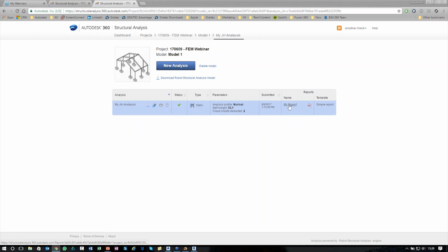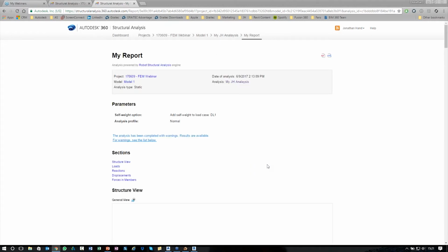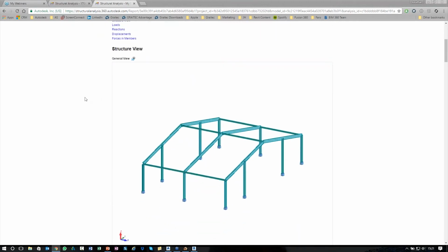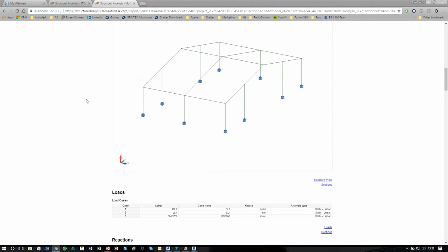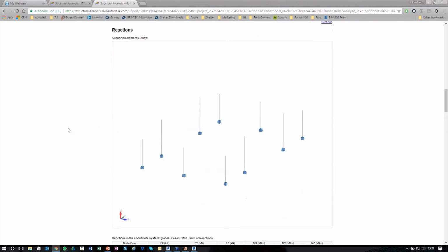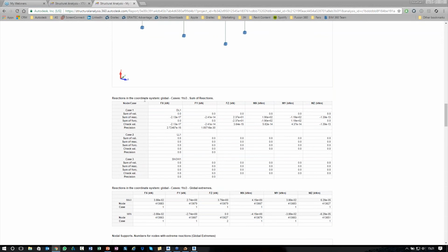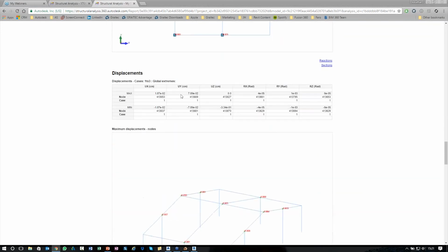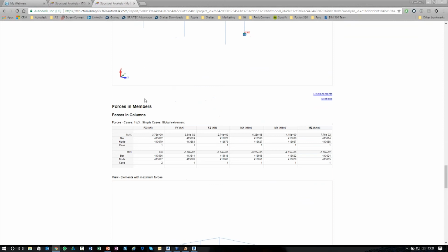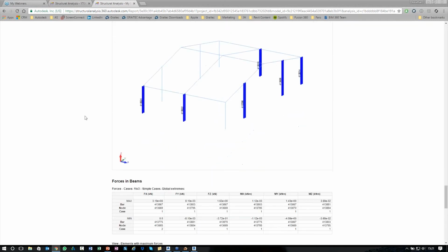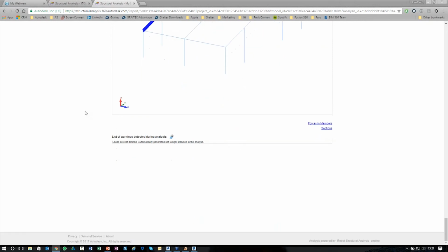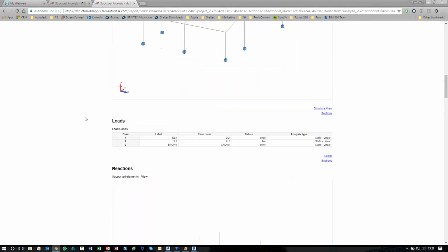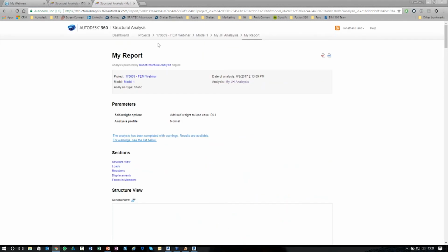And you can see that I've added in a connection. I'm just going to repeat this just before we send this to Advanced Steel. So I'm going to put a haunch connection in just there. I'm going to modify its parameters, and we're going to go with a horizontal cap plate and 50 millimeters. And then we choose this and this, so we can close this down. Let's add a single-sided end plate. So you can start to see very, very quickly we could create a really good structural intent model. So I'm just going to save it.